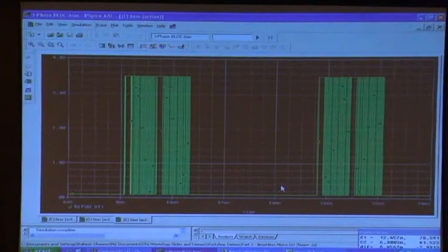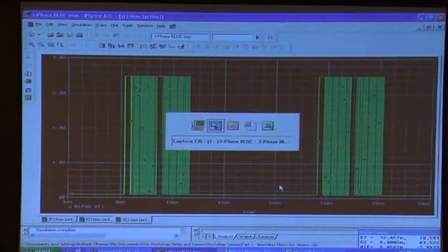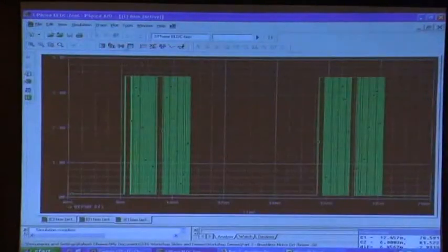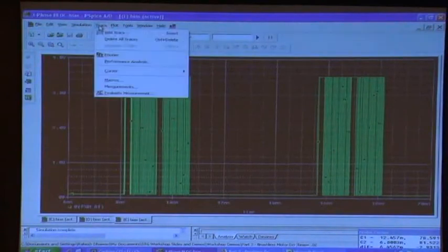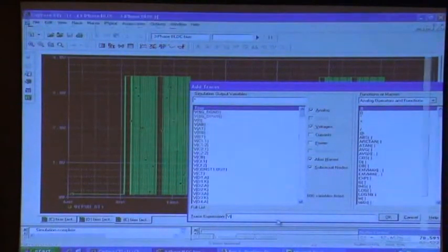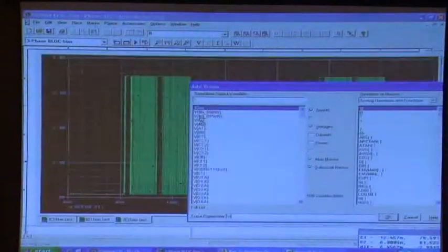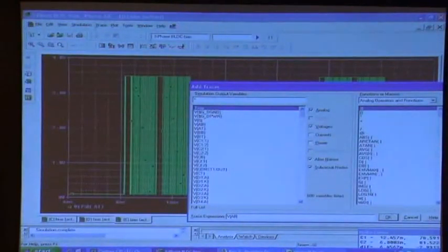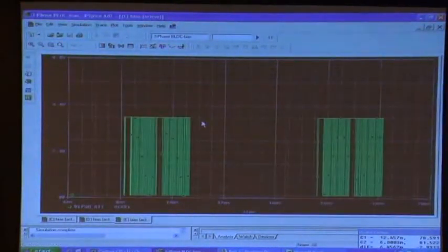And then I can look at also the bottom side. Now the bottom side I can also take from a trace, add trace, and I can just put V. I think let's see if it works. VAB, because we named the node as VAB. So that's your bottom side.